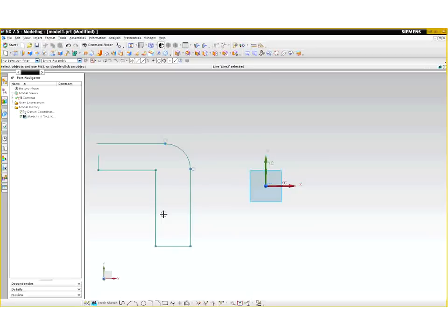And the next one I want to show you is the coincident constraint. So what we're going to do is select a couple points. Now keep in mind I'm selecting the end point of these geometries. So let me pick this endpoint. When I hover over this line, you see at the end there's a brown circle. That's the endpoint. I'm going to go ahead and click that endpoint.